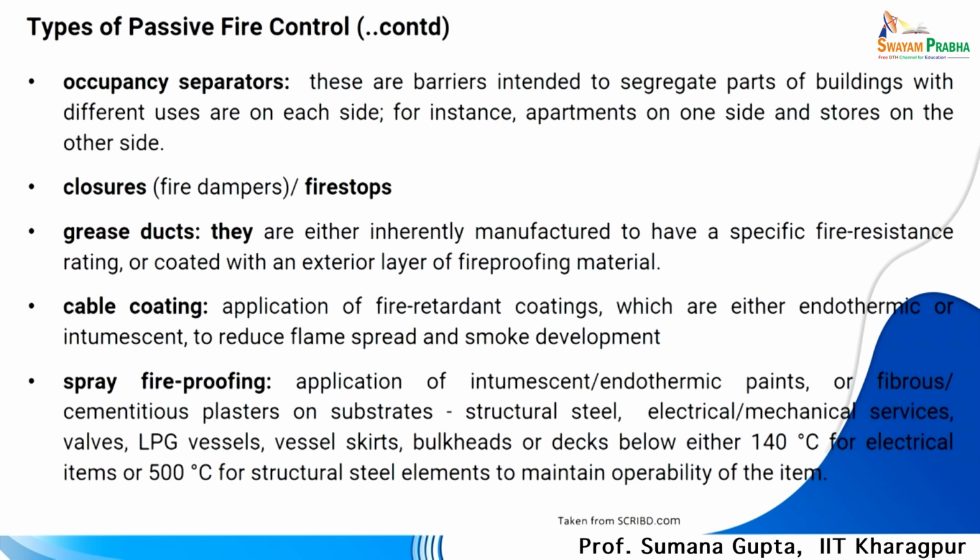Occupancy separator, barriers that segregate the two parts of the building, as we talk about walls. Now comes the second point, closures and fire stops. We can talk endlessly about walls, doors, and windows, but there are various openings within a building other than these. We need to stop them with fire stops or by sealing with fire stop sealants,